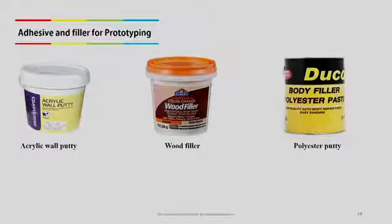It comes in the form of grey color and paste. So, it cannot be used on top of thermocol because you have to mix thinner with polyester putty, and if you apply polyester putty on top of thermocol, it will burn thermocol. So, while working with thermocol you have to put acrylic putties.